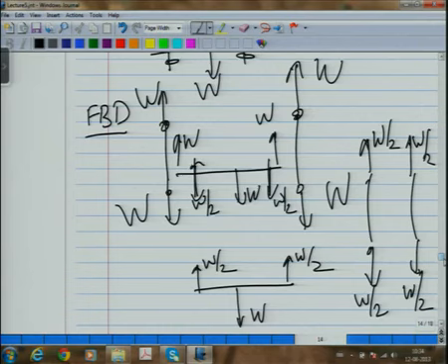So that means effectively the load which is coming is W by 2, W by 2, W by 2 and W by 2 on the 4 bolts, but on the 2 outer bolts the load coming is W. And what they did was they didn't do this analysis and they kept the same bolts. So they kept all the bolts with W by 2 force capacity, whereas in these two bolts the load which was coming was W, so therefore these bolts failed, and once they failed the whole structure failed.